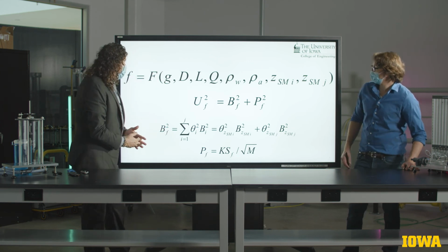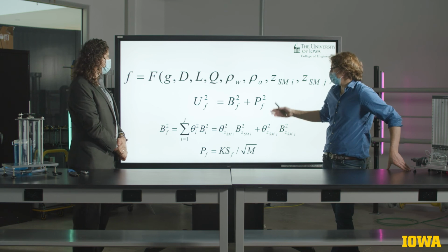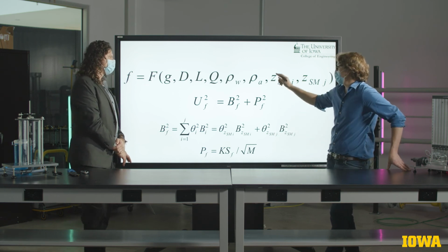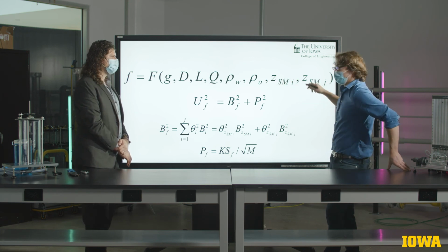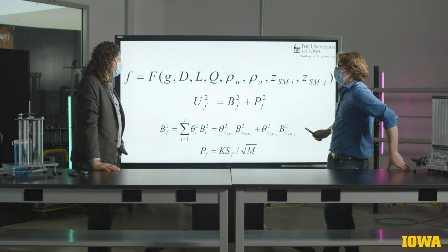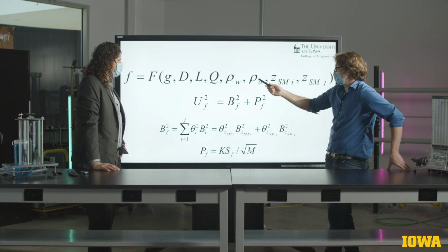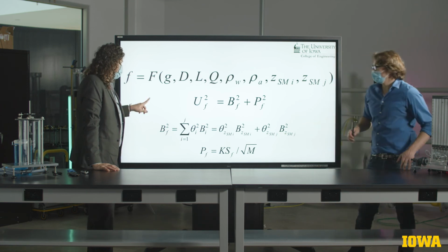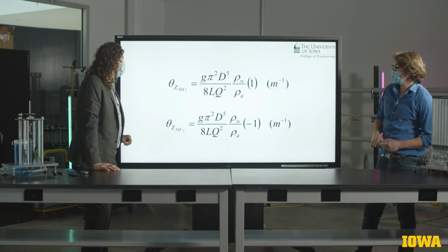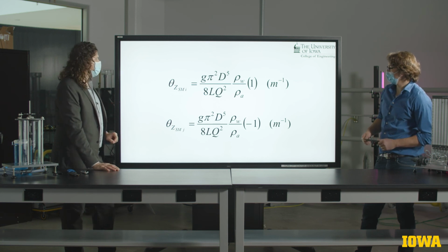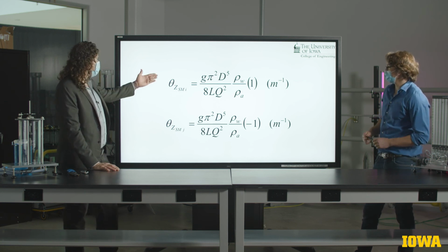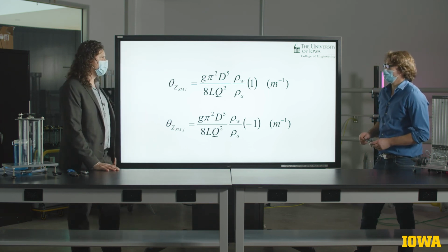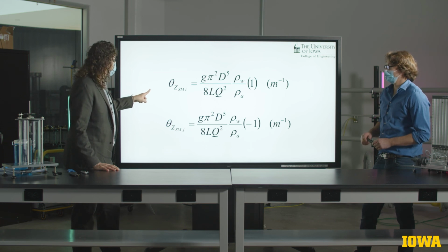That's right. And so the propagation of bias uncertainty is exactly what's shown here, where we need to be mindful of the contribution of the elemental uncertainties in the individual gauge pressure heads, length, diameter of the pipe, etc. So if we use a data reduction equation, these sensitivity coefficients come down to these two equations that we can use then to propagate our uncertainty on our measurements to our estimated variable.